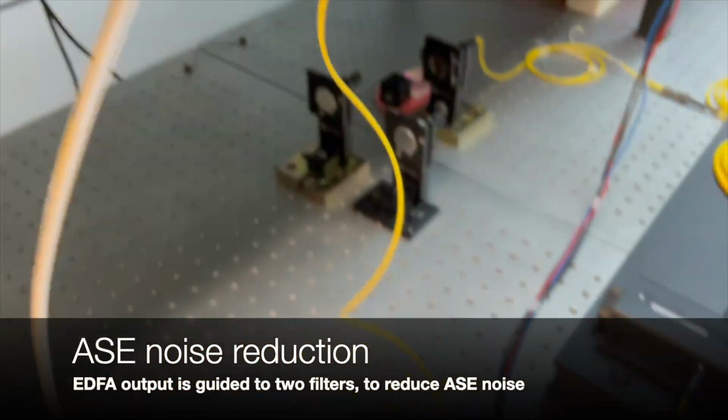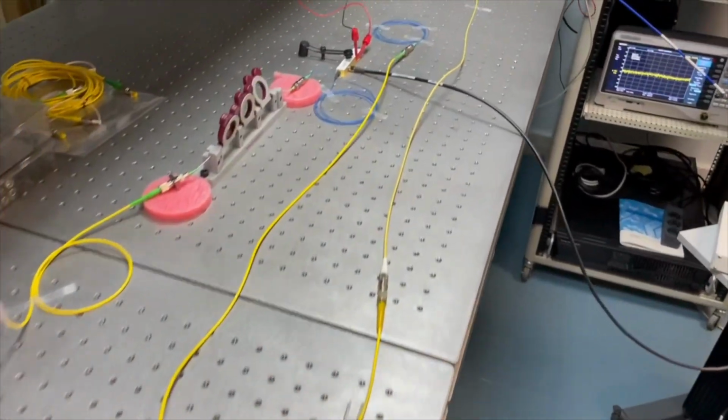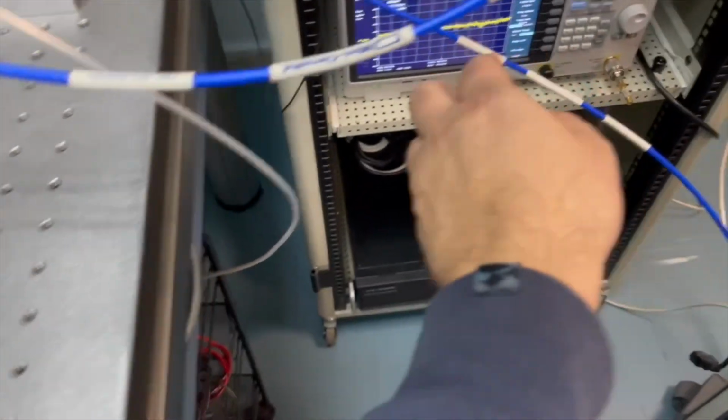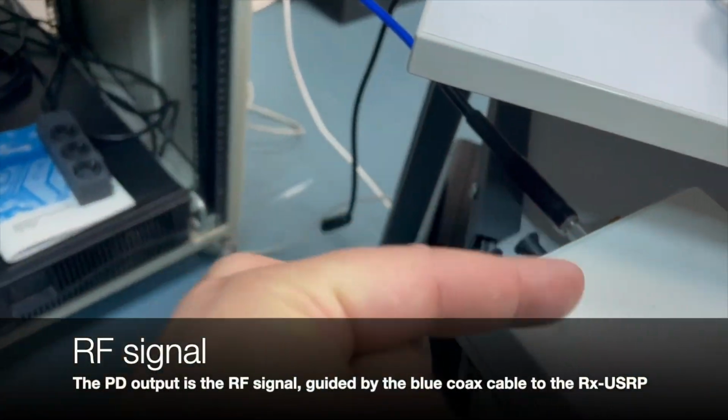EDFA output is guided to two filters, to reduce ASE noise. The filtered light is guided to the photodiode. The photodiode output is the RF signal, guided by the blue coax cable to the RX USRP.